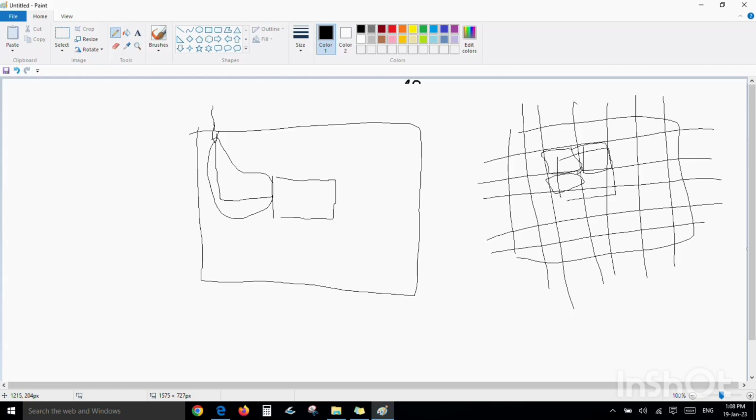So it is easy that there won't be any IR drop like this, whereas if it is done for each and every pin, if one cell is here and one cell is there, that is difficult, right? More routing resources. If I am creating a grid or mesh type of thing, that is easy for doing drop analysis, as I am getting uniform power. This is how much the voltage drop is.